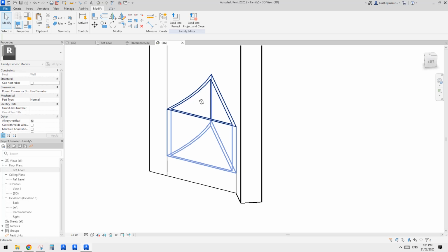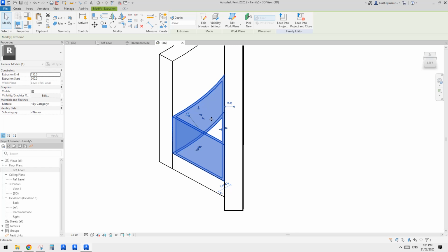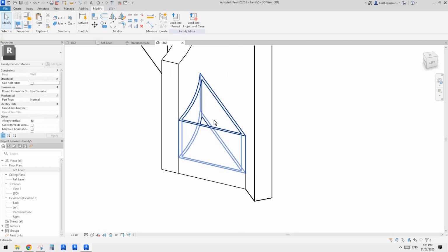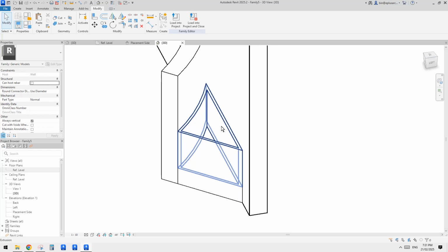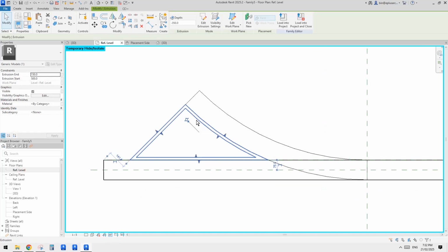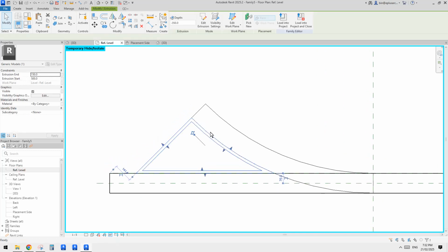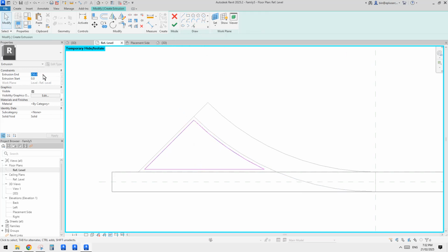And then the soil will be exactly the same, but I'm not going to do it again. I'll leave it to you. You can just create another extrusion and constrain it. Or actually I think we can just pick these 3 edges. So let's try. CS, create a similar, create another extrusion, right? Pick lines with the lock, 1, 2, 3, and then finish and change this one. From 150, so we have the garden bed at 500, so I'll just make the soil finish at 450.